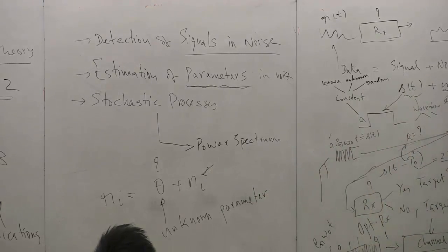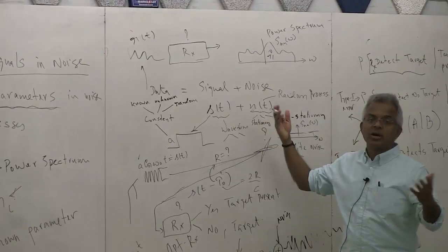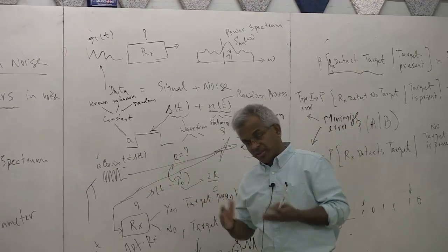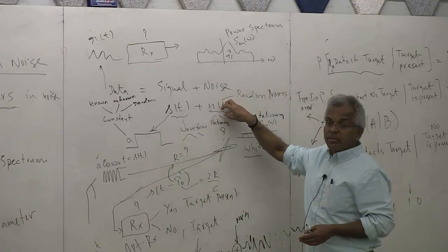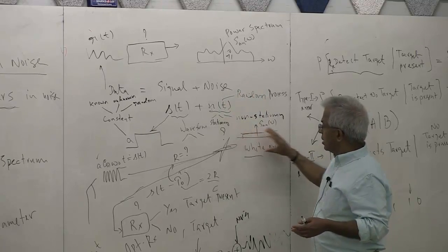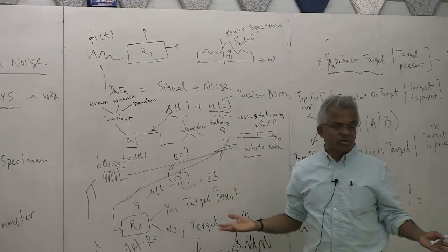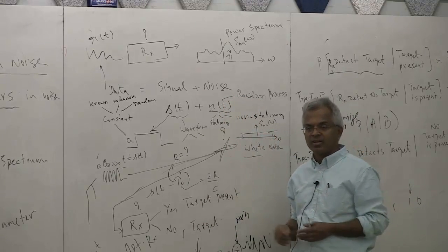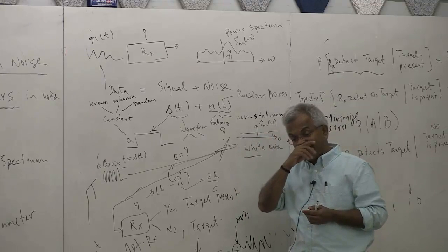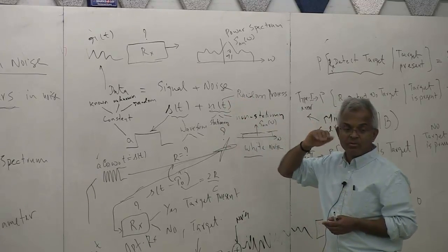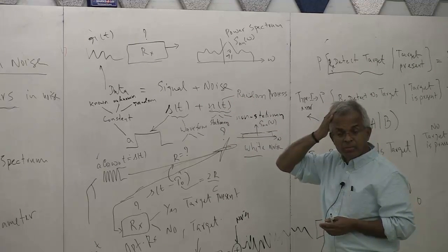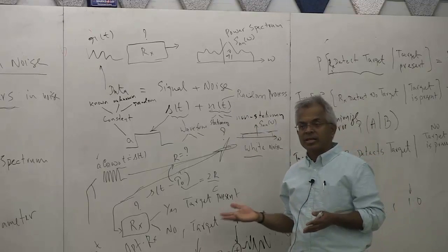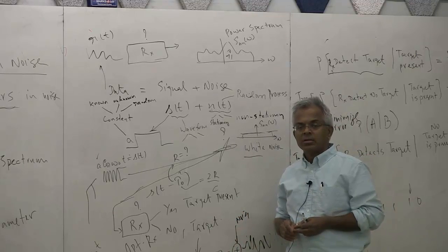And on top of this, one thing I forgot to tell you here is you could say the noise is Gaussian, non-Gaussian, etc. So remember, a lot of things going on. Function of time, that's one concept. The frequency characteristics, that's a second concept on the noise. On top of that, this could be Gaussian. This is not Gaussian. Gaussian is a completely different thing. At least you know what a Gaussian random variable is. So we'll define what we mean by Gaussian for stochastic processes also. Or it could be non-Gaussian, like underwater noise.